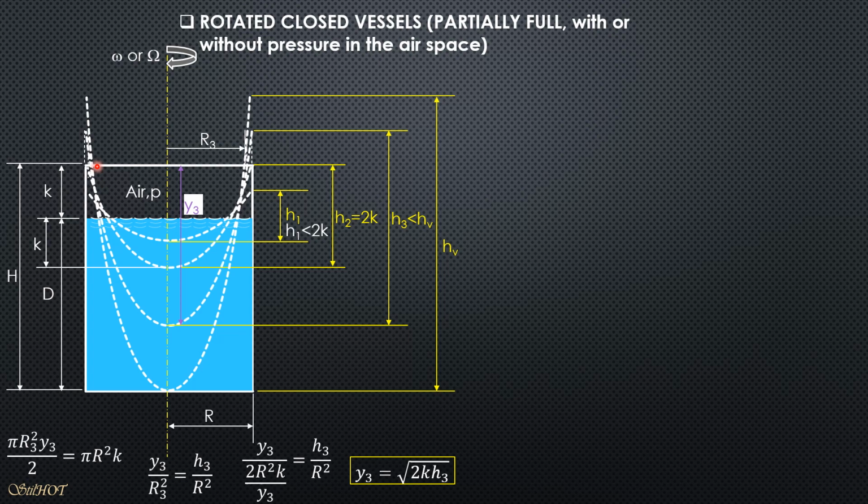Since there is only one base and the radius is denoted by r sub v for that case, the volume of air inside the tank is pi over 2 rv squared times big H, and it is equated to pi r squared times k, the original volume of air. Now, establishing rv squared, it is equal to 2 r squared k over big H after canceling out pi.